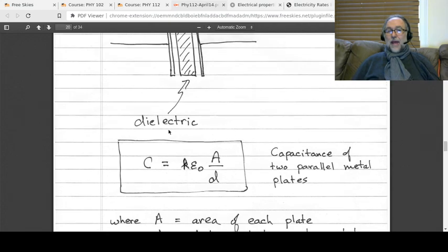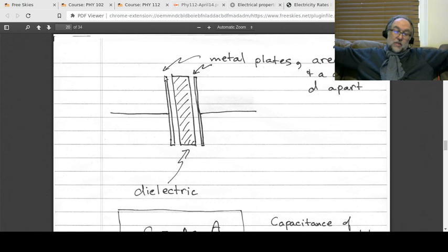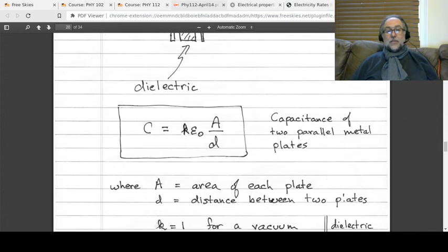All right, remember what a capacitor does. A capacitor basically accumulates charge. The bigger the plates are, the more area there is to accumulate charge. Remember, the negatives don't like being near one another. So if you create a big area on this plate here, say that's the negative plate, you're giving more space to those electrons to spread out, and they're happier being there. All right, and so the bigger the area, the bigger the capacitance, and you can see that in the formula because A is on top. You double A, you're going to double the capacitance.